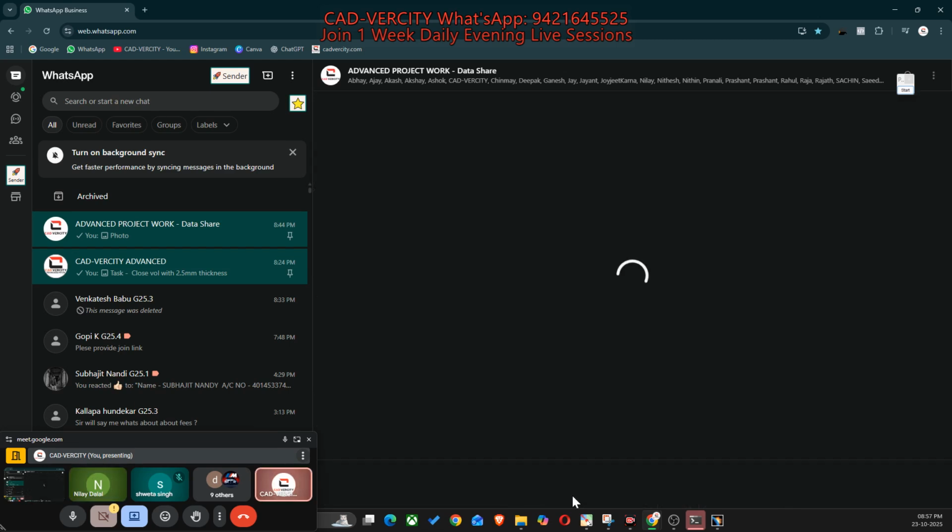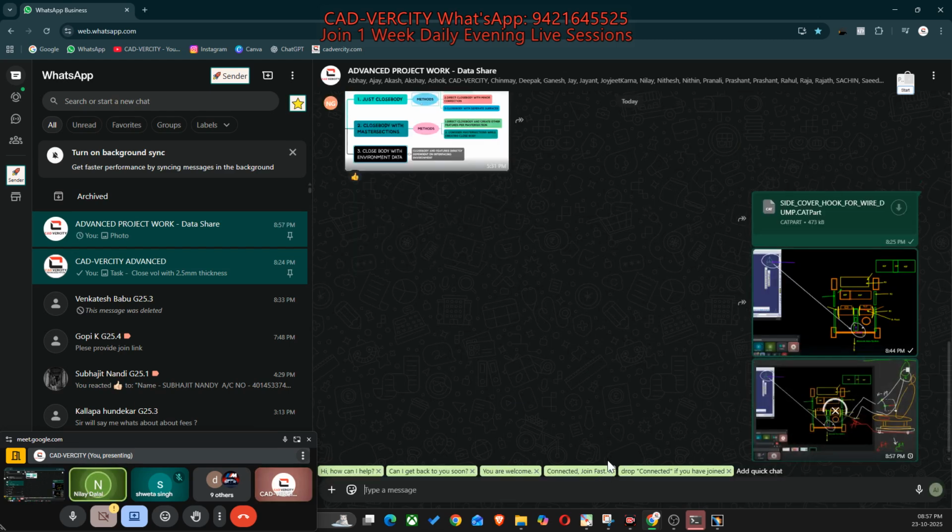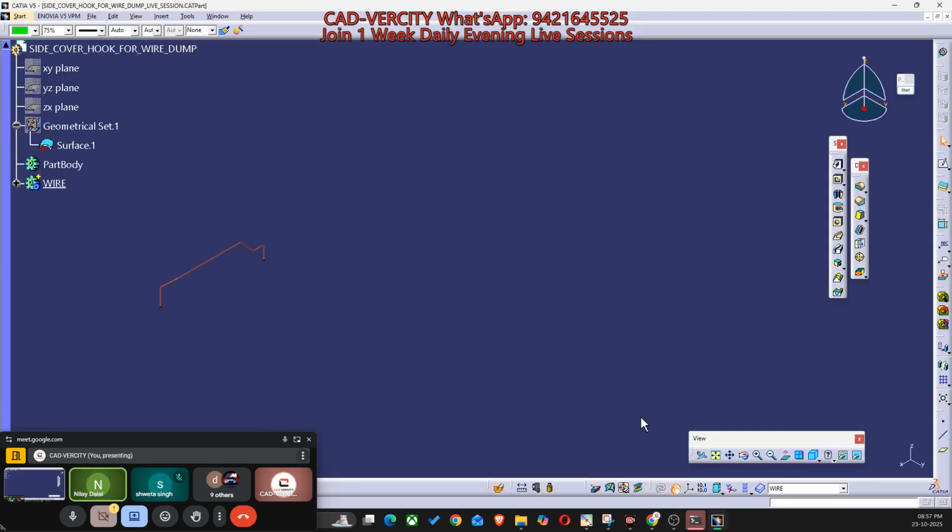Yes. And during the designing of the seating system, we get the seat reference position through the customers and OEMs. Okay. So at the end, after designing the seat, we need to match H point and R point, right? Yes. And it is not mandatory to be within that box. See, it is not mandatory.